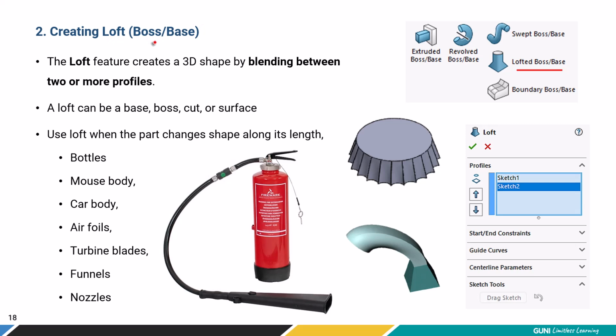Now loft boss base adds material, while loft cut will simply remove the material. So let's first explore loft boss base. Loft features create a 3D shape by blending between two or more profiles.